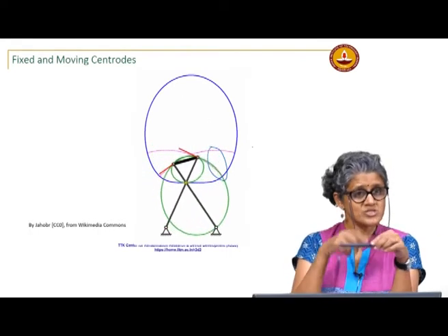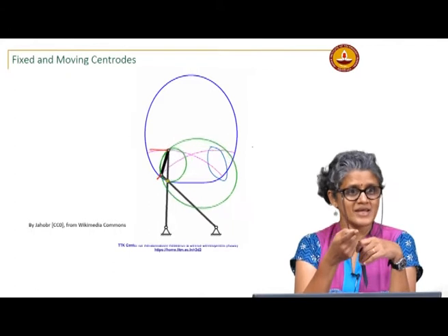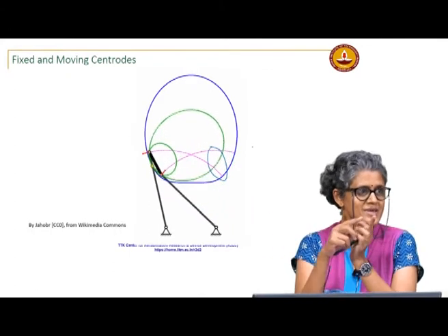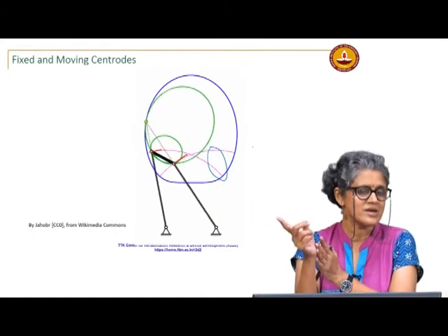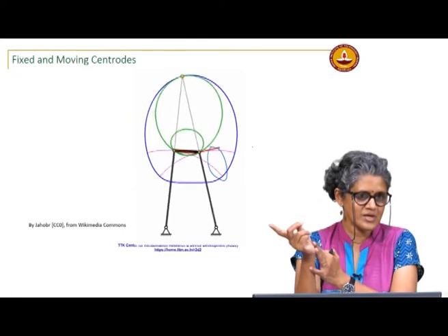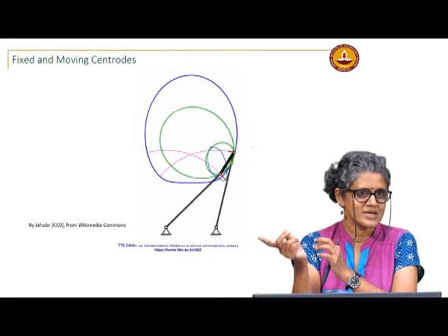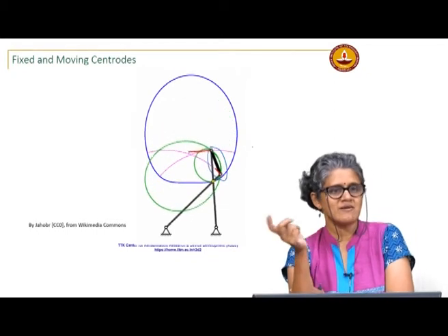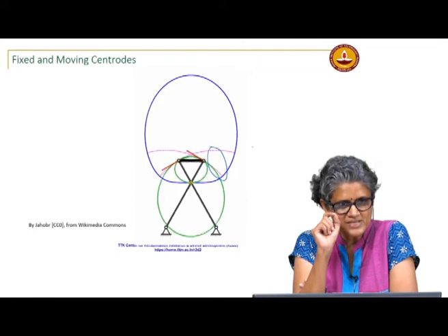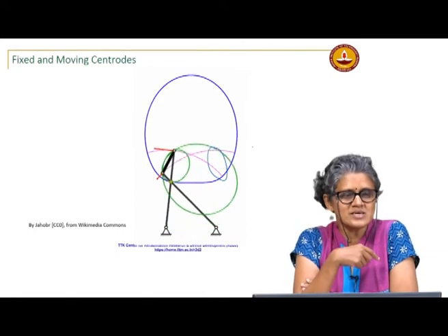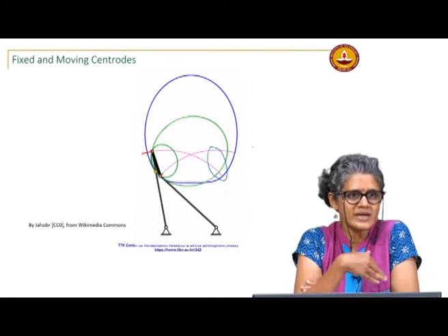Yeah, that point actually reverses direction, because at the limit positions. So, if you consider that as a point on the coupler, that is reversing direction, then all the rockers will have to. All the rockers will have, you know, but we do not really consider that, because it's the degenerate case, you only get a circular arc.